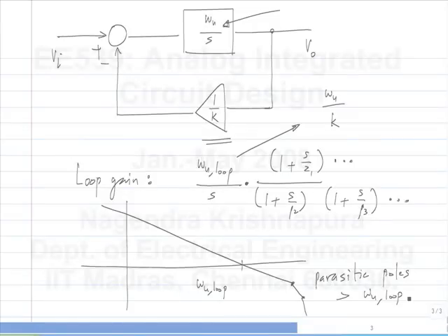So the loop gain has to have this first order behavior up to a point where it goes below unity. Well beyond the point where it goes to unity, you can have parasitic poles and zeros, and they won't affect the system too much. They do have an effect on the system, just like we have analyzed, but if they are well away, then they don't have any effect.